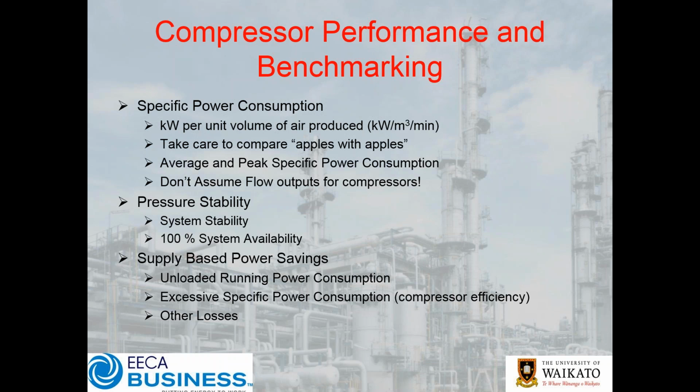Okay, you need to be careful that you're comparing apples with apples. Are they with the same reference conditions for your airflow and inlet conditions and so forth? Is it input power or shaft power? Are the motor efficiencies taken into account, etc., etc.? Then you need to look at what your average versus your peak power consumption is. Now, just a note here, and we've got a little example we'll share in just a minute, don't assume the output flow for the compressor.